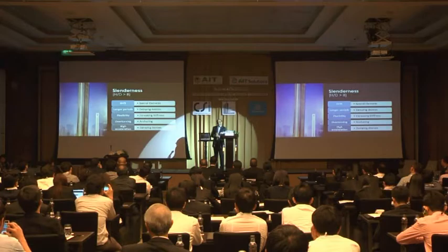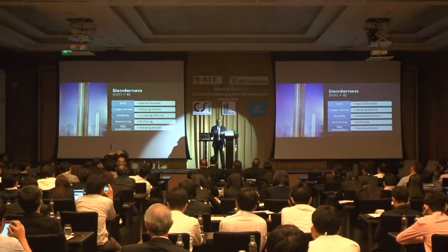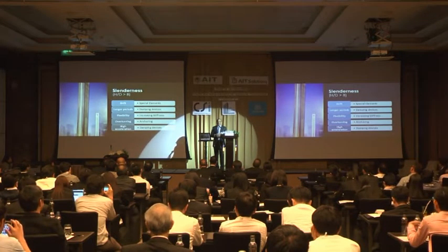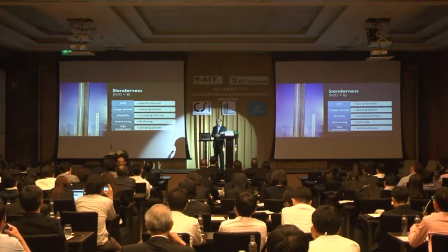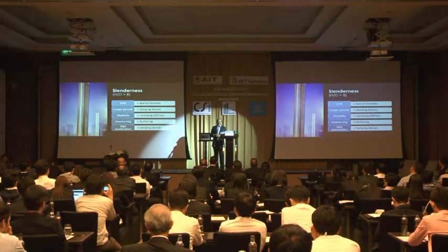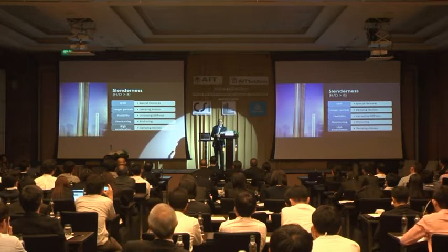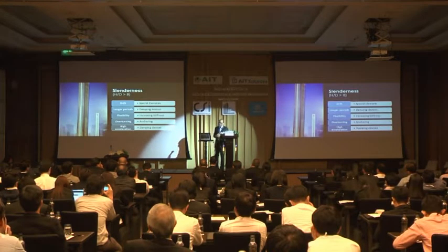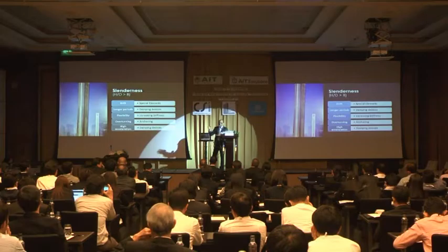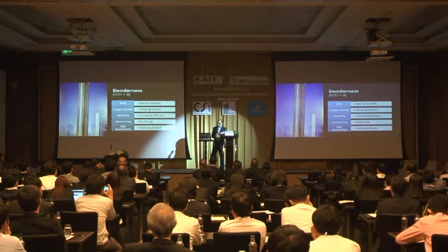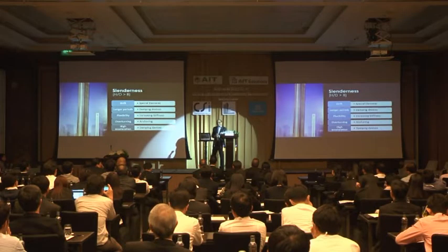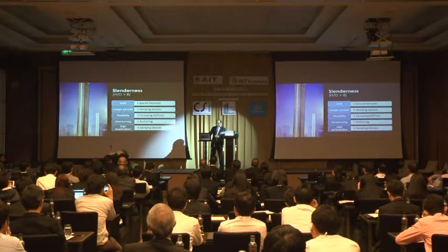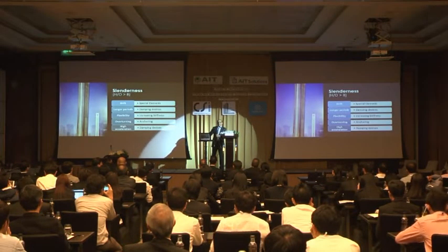Overturning, buildings may be overturned. We need anchorage, we need columns. A lot of buildings now, standard column buildings that we have evaluated, their columns become in tension. That's just not good, because it really requires a lot of detailing on anchorages, on splicing, on many things. A column in pure tension is not a good thing. So if the columns become in tension, even with the effect of the gravity load, that means the building is really slender. High acceleration, the buildings may experience high acceleration, so we will need, again, dampers of different kinds. So slenderness is one of the key challenges.